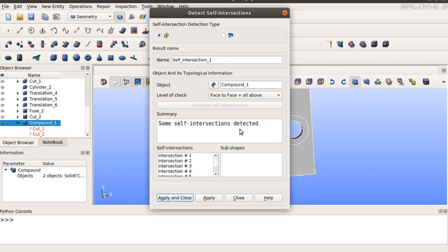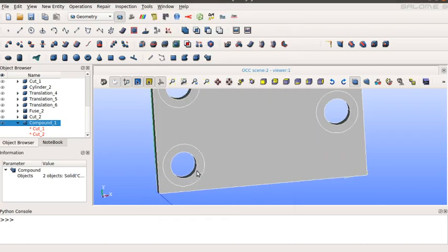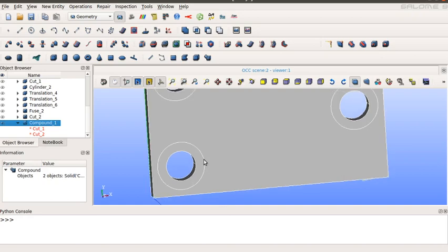If we go for structural FEA with the Calculix solver, then after running the solver, when we view the result, we can see the stress concentration nearly here, in the boundary between the free and fixed region. We will see stress concentration that has to come to this wall, but it will be shown here.